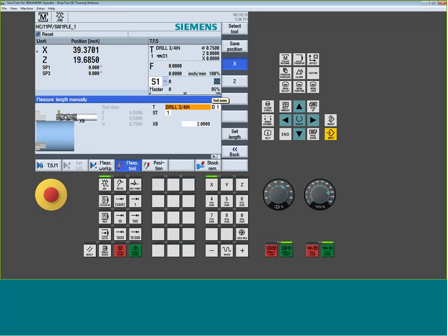And this would be the same thing with an end mill for a live tool or whatnot. So yeah, I can come in and I can set my length. Let's say I set my length to 2 inch. And you see how it's saying, oh, well, you're really 275 away, because it's taking this diameter into account. So that's fine if I'm bumping the side of the tool.